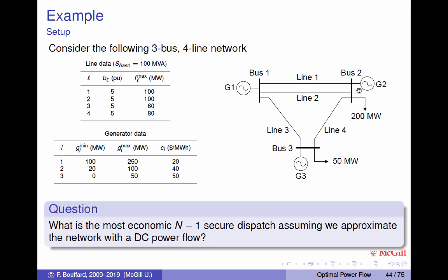So here we are injecting 1 megawatt at node 2, and we are extracting it at node 1. So when we have that 1 megawatt going here, we have twice the series reactance, and here we have one time the series reactance.